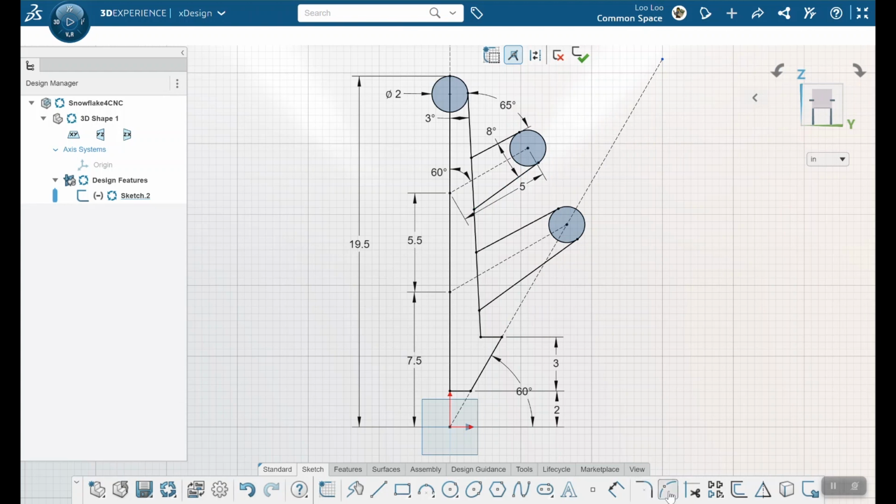Now I can go ahead and trim away unnecessary lines to then form these solid shapes in blue. This solid blue shape ensures that I have no errors as I move ahead and make this 3D. Here I'm trying to close off the last spur with the angle that's created. I just want to make sure that the line and the circle are coincident and clean before I trim off everything and make sure that it's airtight.